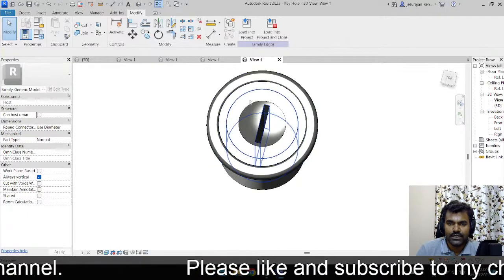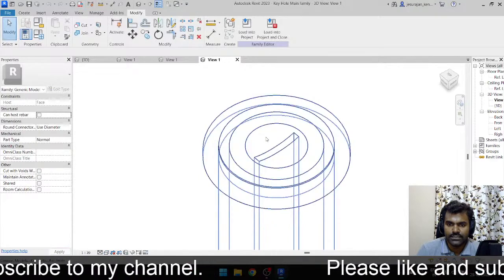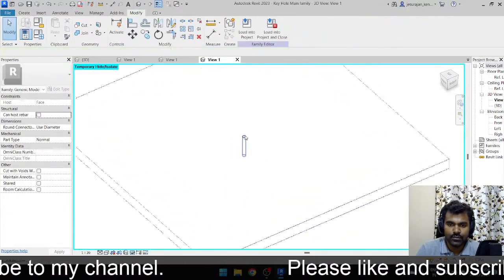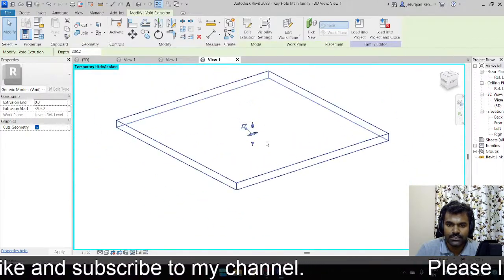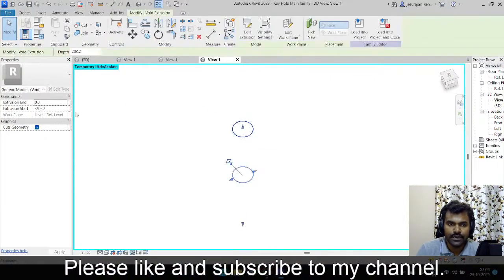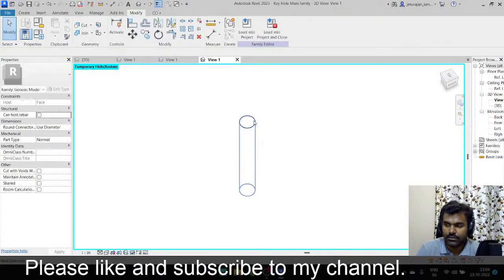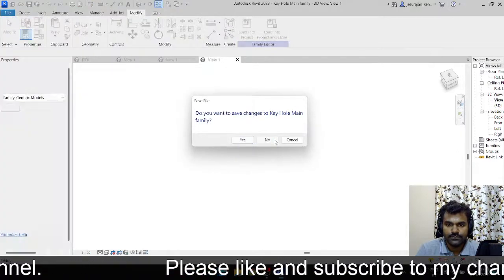Okay, fine. So when I'm loading into the face based family, I'm not going to save this here. You can see this is the face based family. So if I hide this family here in the face based family, you can see a small void that's cutting the face. So that's the only element that's going to cut the plywood. Okay, so I have used a depth parameter to adjust the depth of the void. Okay, so that's going to help us in the study table family. So if I close this here, I'm not going to save it.